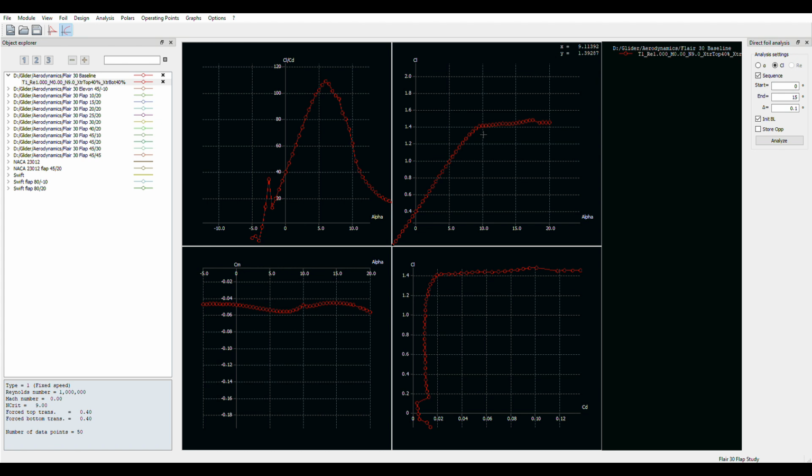The root of the wing might be operating in a stall in this mushy area over here to the right of the stall. And he doesn't know that because he's not getting a significant burble from separated flow, because this airfoil just kind of mushes along at that angle of attack. There's no break in the stall. So the inboard part of the wing might be stalled, and the majority of the wing is still flying. He's up at a high angle of attack though.